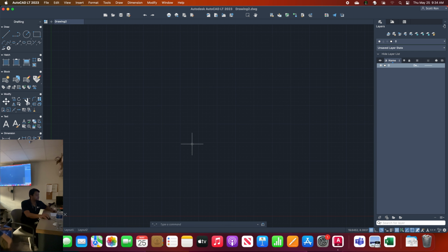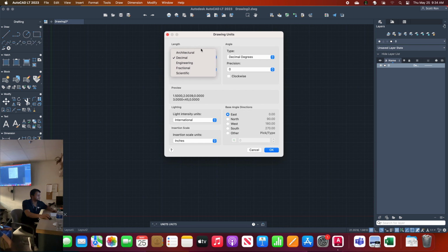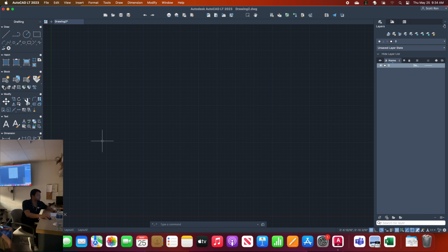Okay, new. Remember when you open a new drawing, what is the first thing you do? Units. Decimal, architectural. Your drawing is going to be in architectural format, which is feet and inches.